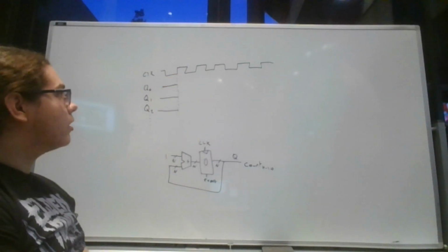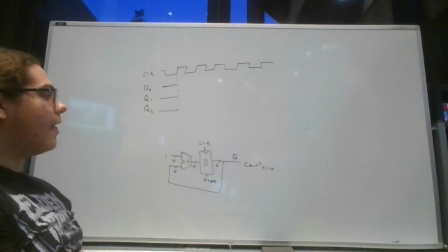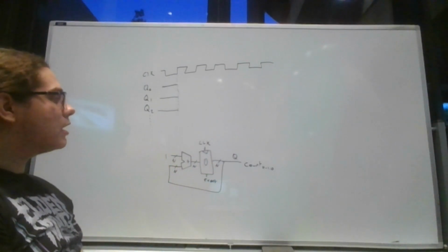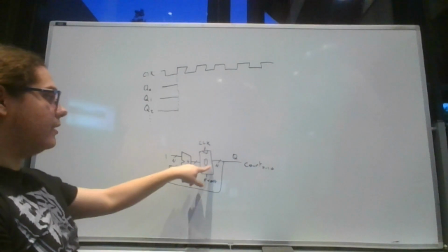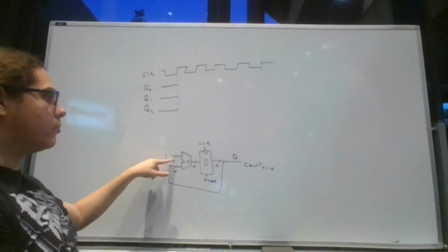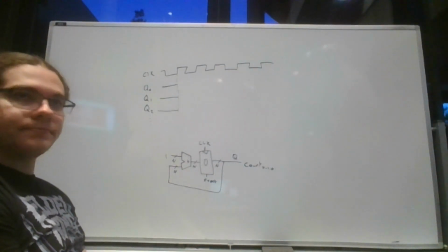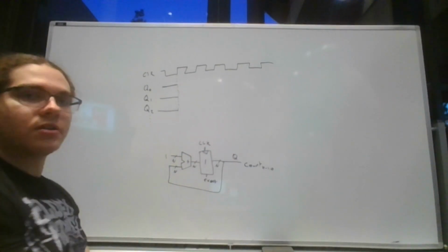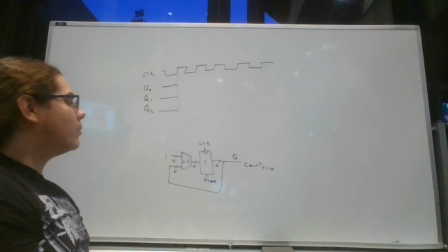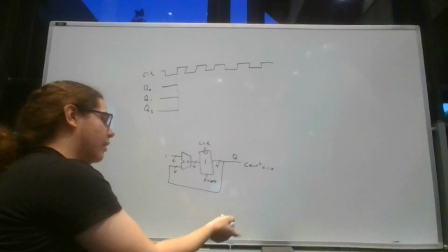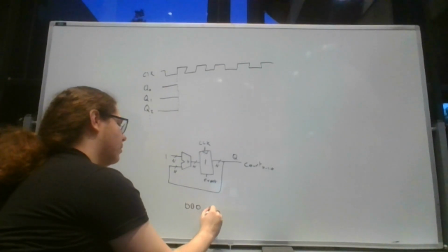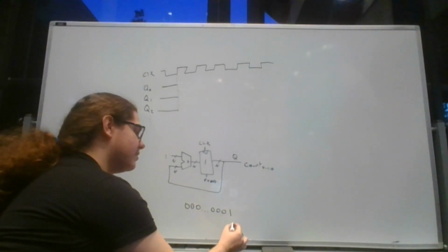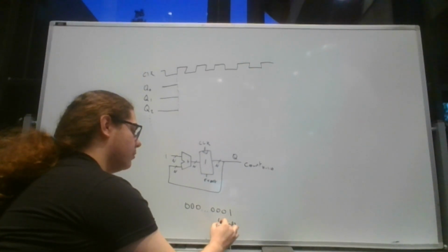However, once that rising edge of the clock hits, we read in the value from the output of the adder into my register. The output of this register was originally 0. 0 plus 1 is 1, so it's going to read in a 1. So the register is going to store the value 1. Whatever the binary encoding is, however many bits it is, it's going to look something like this now: a bunch of leading zeros with a 1 at the end, where this is the least significant bit, Q bit 0, Q bit 1, Q bit 2, etc.